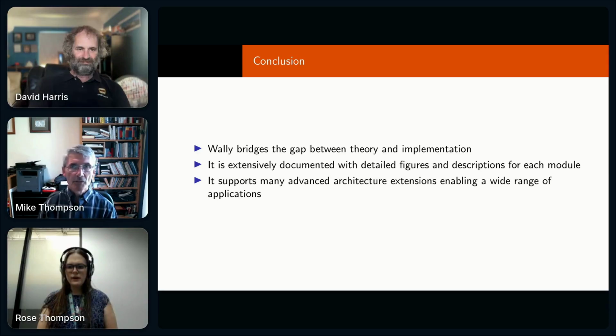Yeah, and the RISC-V standard makes it relatively straightforward to add custom instructions, and I think that tends to attract a lot of people. But as soon as you create a decoder in RTL, changing the instruction set or adding your custom instructions, now you're actually opening up the decoder, opening up the pipeline. So I'm going to offer an opinion here on the question. My first response to the question would be: have you considered why you're interested in creating a custom instruction? The RISC-V ISA is very rich.